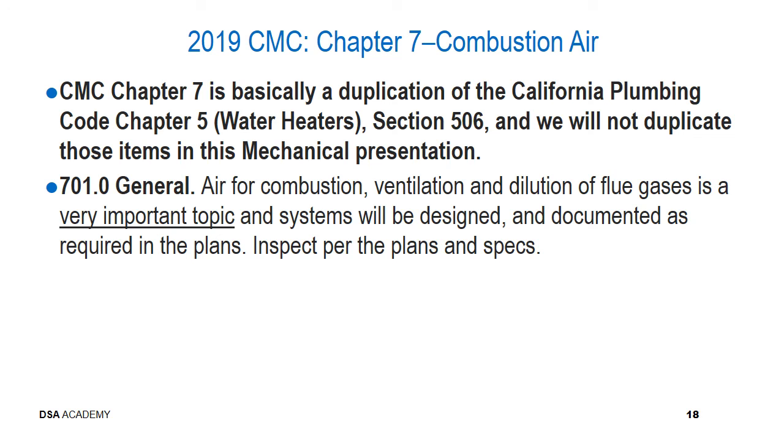In general, however, air that's used for combustion, ventilation, and dilution of flue gases is a very important topic, and the systems will be designed and documented as required in the plans. So the best advice to give, or simplest advice to give, obviously, is to inspect the installation of any combustion air systems based on the approved plans and specifications.